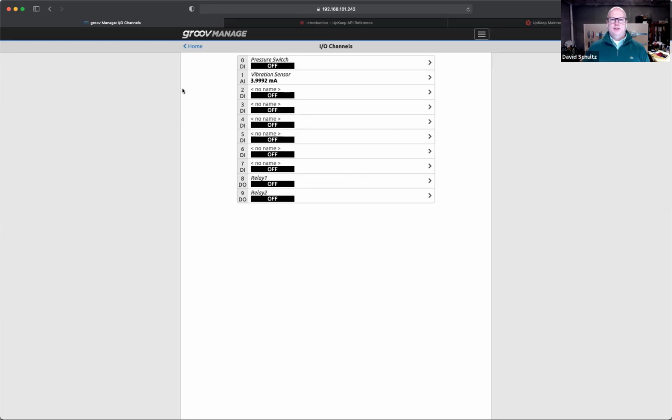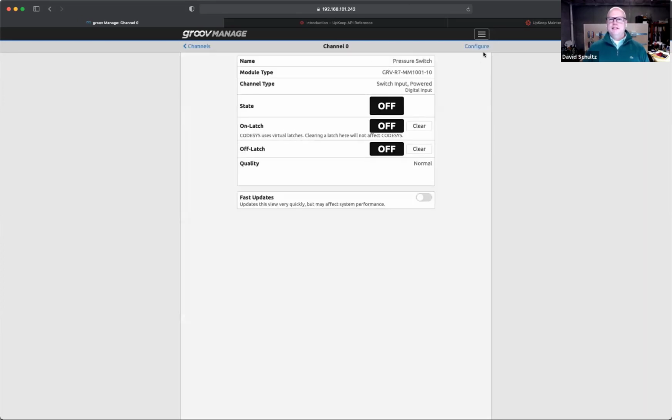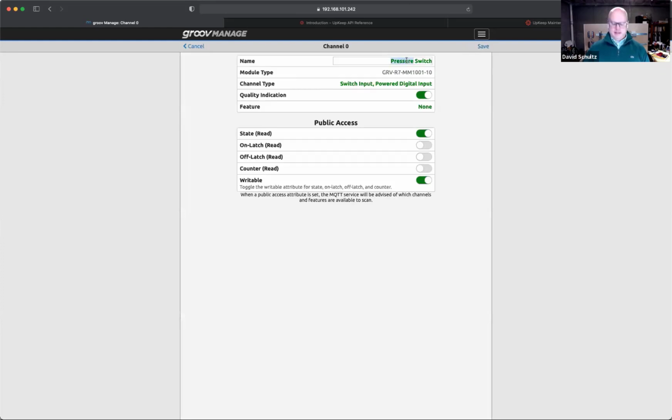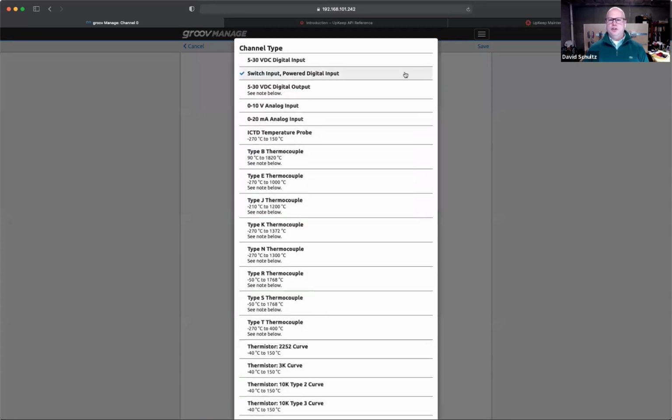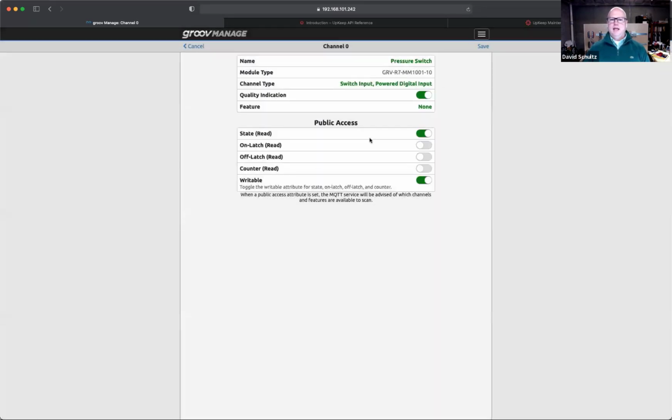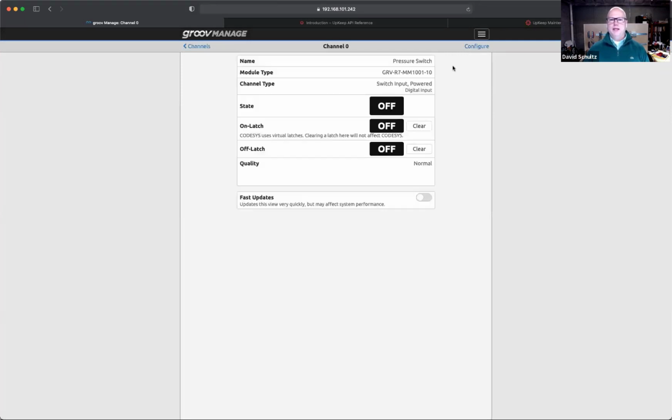So the first thing to do, let's go ahead and get into the Groov Rio itself. And I see I've not called this the right thing. It's actually going to be, oh wait, no, that is the right thing. Sorry, my bad. This is the pressure switch. So you want to go in and edit that. Again, it's just a switch input coming right off of the Groov Rio itself. And then that's all you need to do to set this up. So go ahead and hit save.